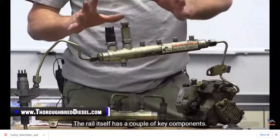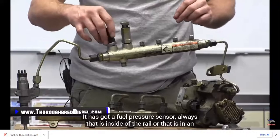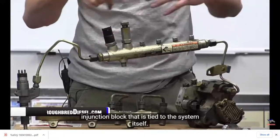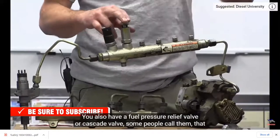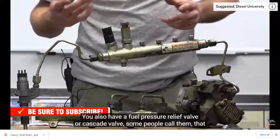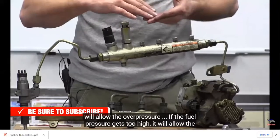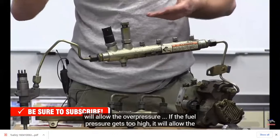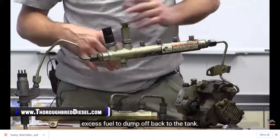The rail itself has a couple of key components. It has a fuel pressure sensor, which is either inside of the rail or in a junction block that is tied to the system itself. And you also have a fuel pressure relief valve, or a cascade valve, some people call it. If the fuel pressure gets too high, it will allow the excess fuel to dump off back to the tank.